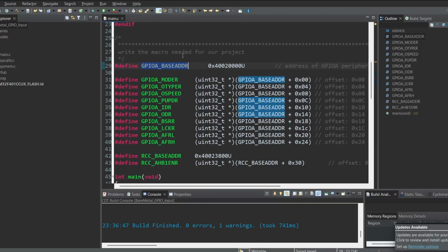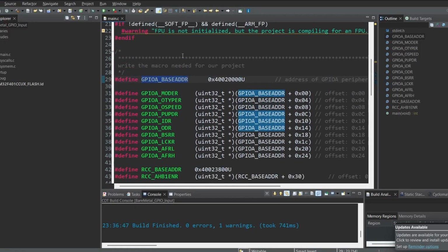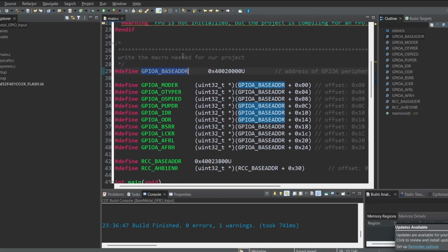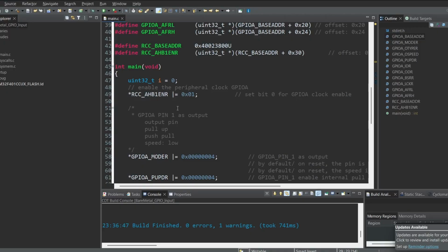and gpio.c. There we will write our structure, the GPIO handle structure, and a user-defined structure for how the user wants to configure the pins. So for that we will write structures. One structure will be for these registers, to access the registers, the handle structure, and one will be for the input, that is, how the user wants to configure the GPIO port pins, either input, output, analog, or alternate functionality. So that we will write in the next lecture.